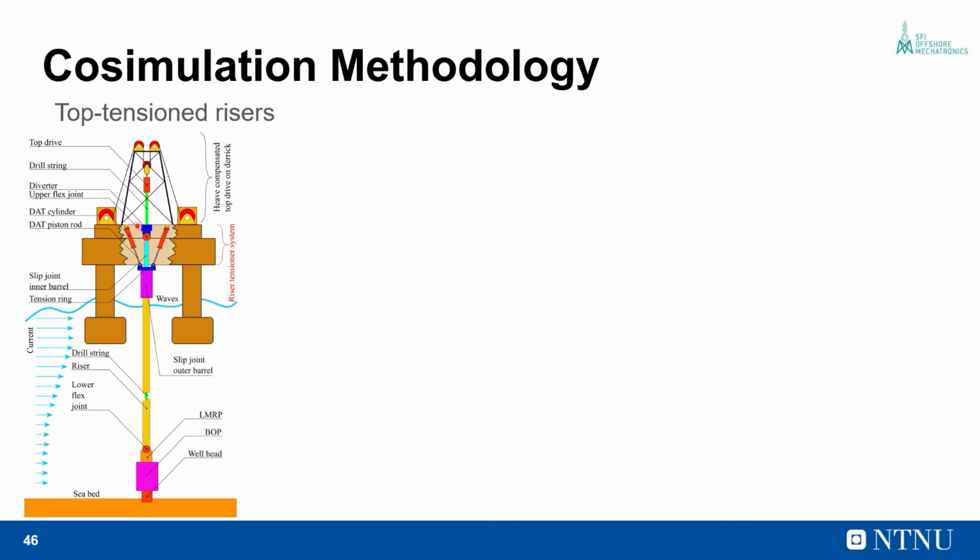And had the riser not been tensioned by using these tensioning cylinders, what would have happened was that when the platform moved down, if the top end of the riser was fixed, then the riser would buckle. And if the platform moved up, with the top end being fixed to the platform, then excessive tension would be applied to the wellhead and the wellhead would be damaged. So that is why we use tensioning cylinders to hold the drilling riser in a near constant tension.